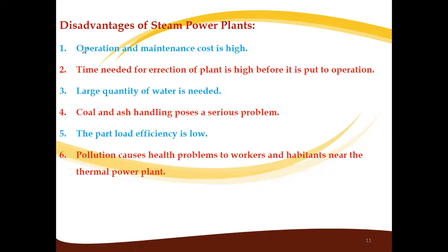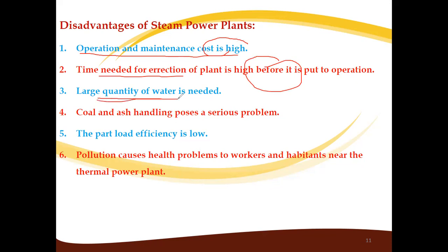So first, the operation and maintenance cost is high for this thermal power plant, because we have a number of parts and all these parts are mechanical parts. So operation as well as maintenance cost will be high. Second, the time needed for erection of the plant is high before it is put into operation. Next one is that a large quantity of water is required, because we convert water into steam. So we require a large quantity of water.